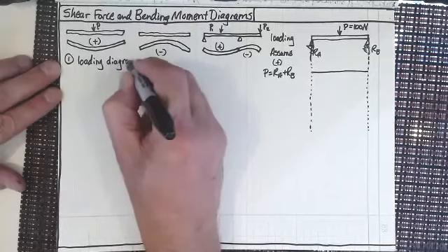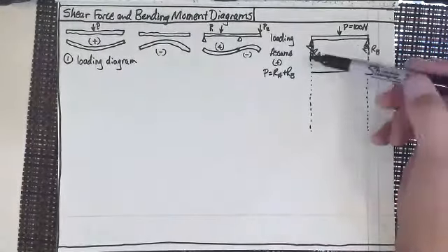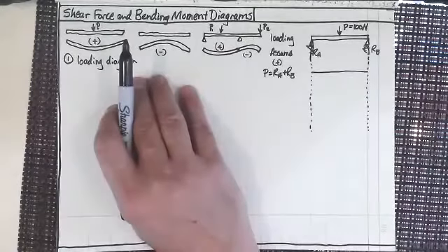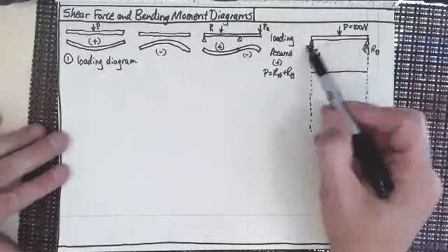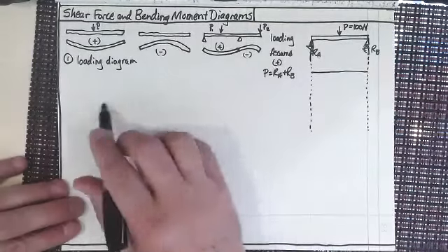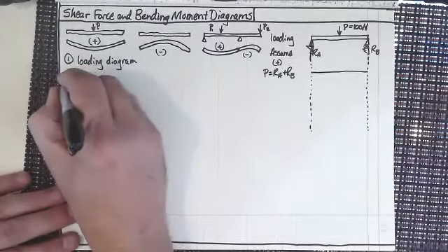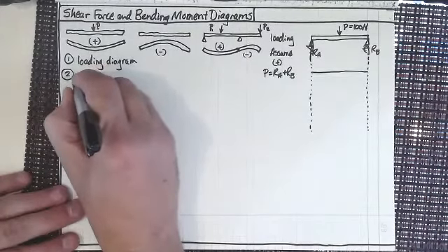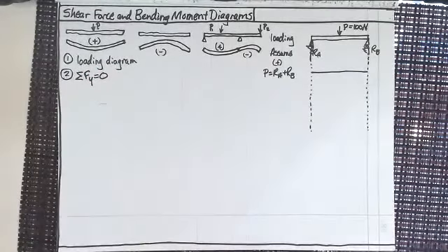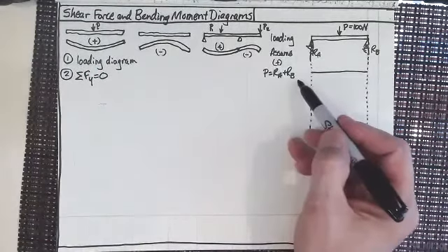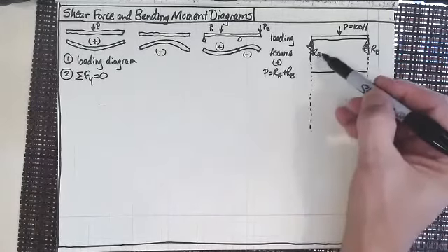And you, or a civil engineer, or electrical or mechanical engineer you're working with, draw it up and look at all the loadings placed on the bridge, on the floor joists, things like that. So we come up with a loading diagram. Then we sum the forces in the y direction equal to 0. That's the second thing that we do, and we've done that, right? We summed them equal to 0. That's where we got minus P plus R sub A plus R sub B.